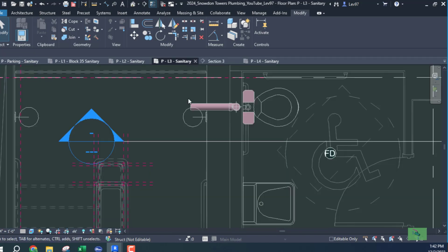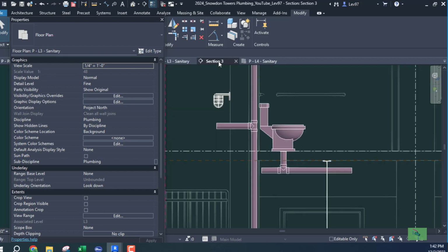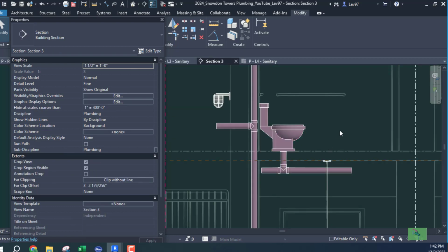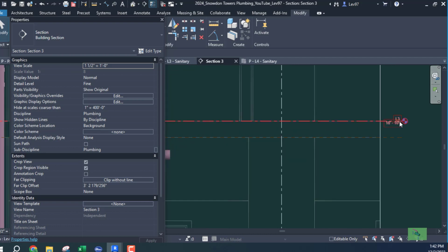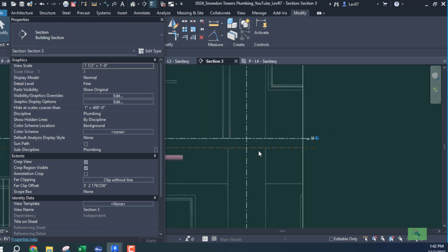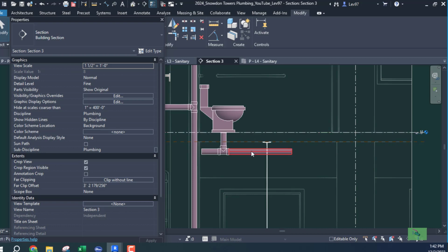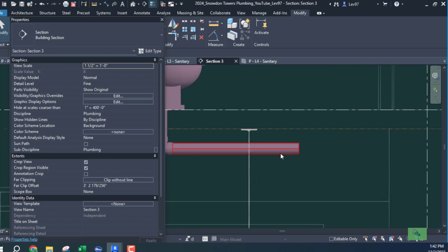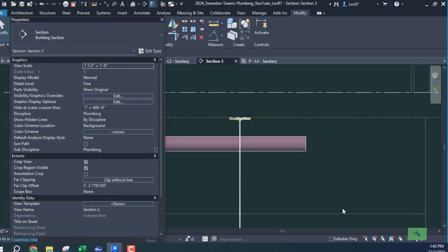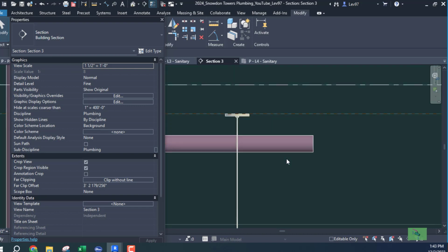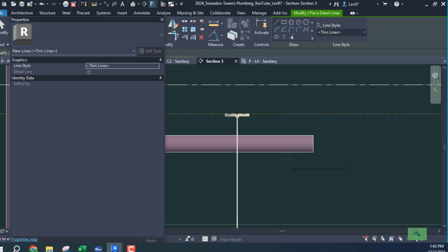So as you go through this, now you see that my pipe is not showing up. And it looks like it's going to be a view range issue. And so looking at this, I may need to come down. It's probably going to say 0, 0 at 11.3, okay? This is 11.3, and I need to go below depth to look at this, okay? So let me turn off the linked model. I want to go below so I can get all of the pipe.